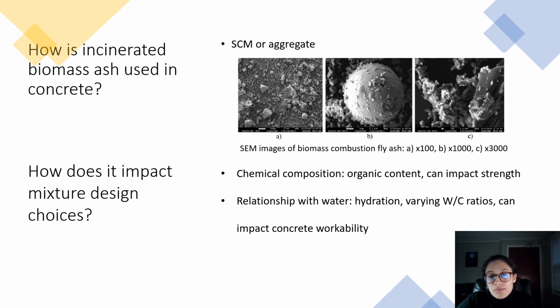I think one of the biggest factors is the fact that its chemical composition has a lot of organic content, and it can be varying depending on what you use. So this could definitely impact your strength because of the structures that could be built up, and also the relationship with water, because you may have a longer hydration process, you may have higher water to cement ratios, and that impacts your concrete durability.